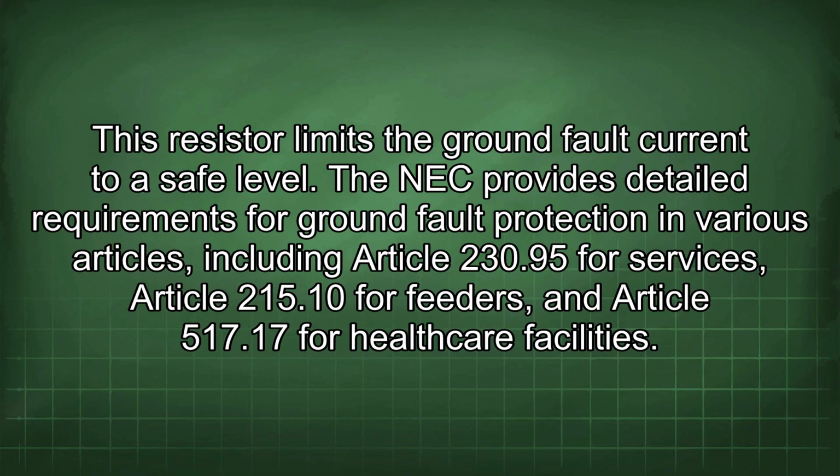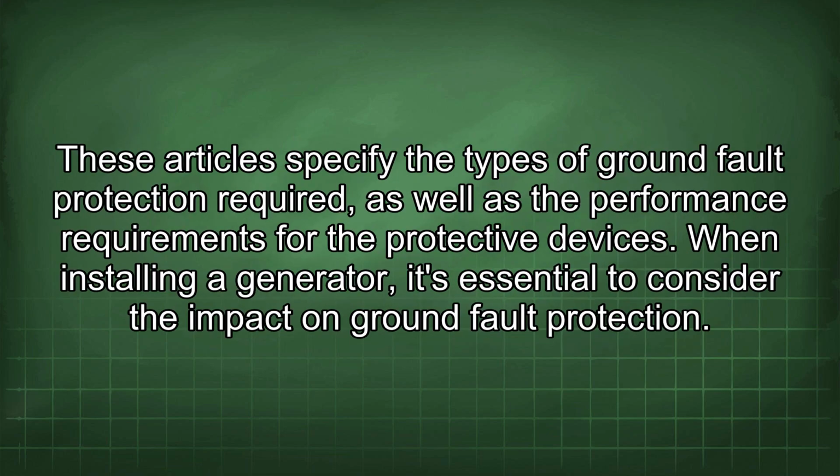The NEC provides detailed requirements for ground fault protection in various articles, including Article 230.95 for services, Article 215.10 for feeders, and Article 517.17 for healthcare facilities. These articles specify the types of ground fault protection required, as well as the performance requirements